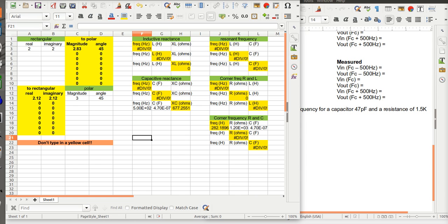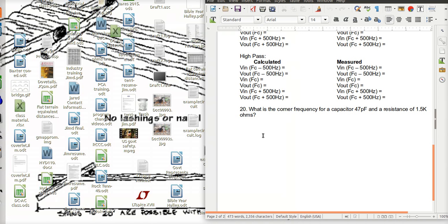Basically, you're going to use two devices, and then you're going to swap them. One way you can put them in, it'll wind up being a low-pass filter. The other way will end up being a high-pass filter, and you can reason them out. I think that's the best way to do it, as opposed to trying to remember certain configurations or certain filters. I think it's better in the long run for you.